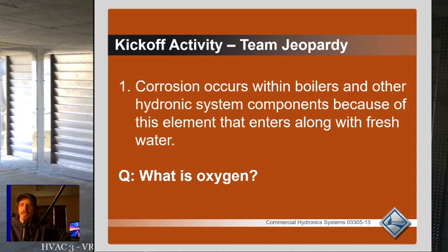That's why we purge it with nitrogen, so there's no oxygen in there while we're brazing, so that we won't form oxides on the inside of the pipe. So oxygen is kind of the catalyst for all these different types of corrosion. But even though there's water inside the boiler system, once you've bled all the extra air out, there's really no free oxygen in there to cause corrosion. So that's why you can run these things in steel.